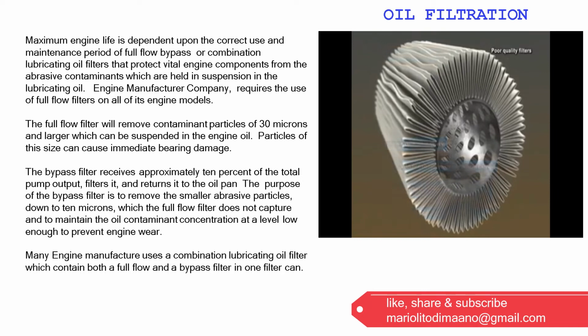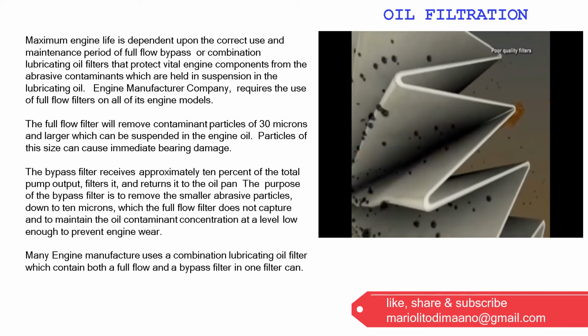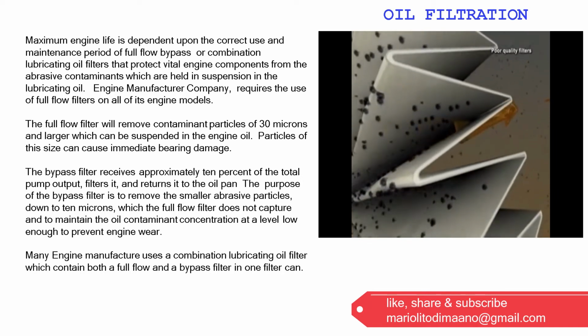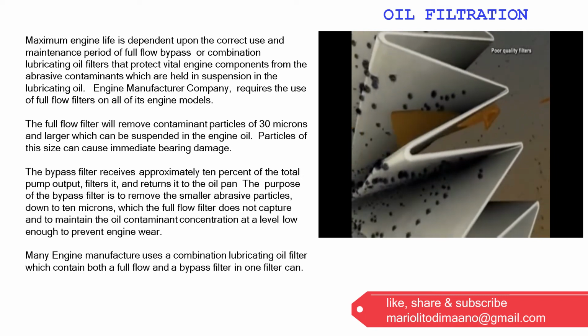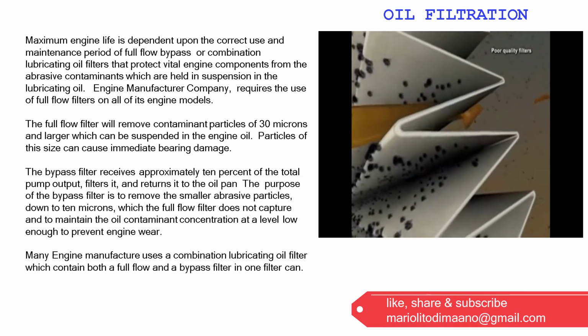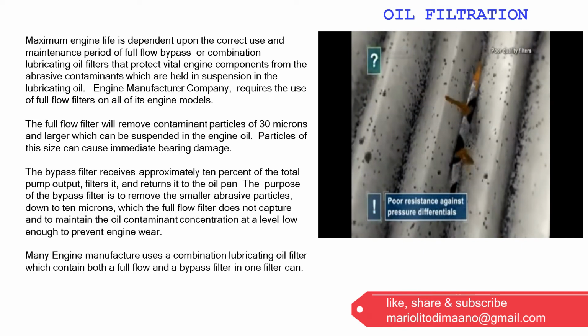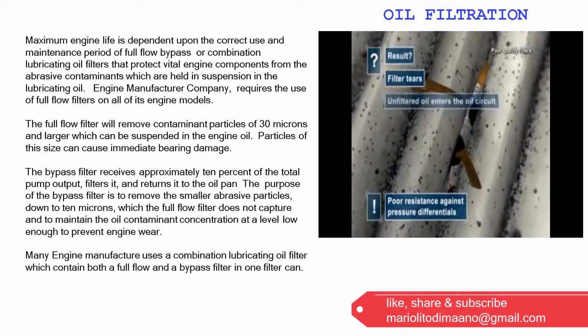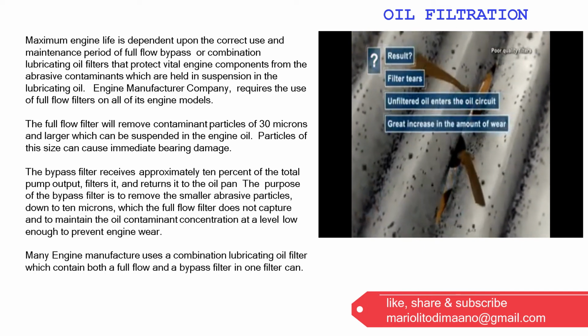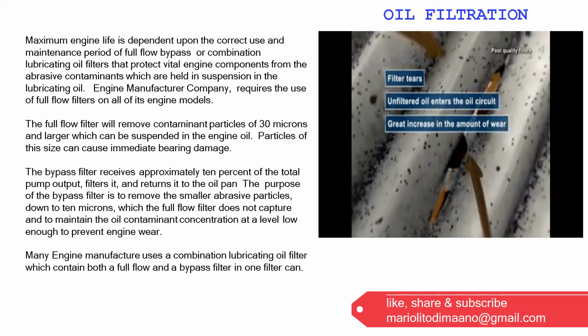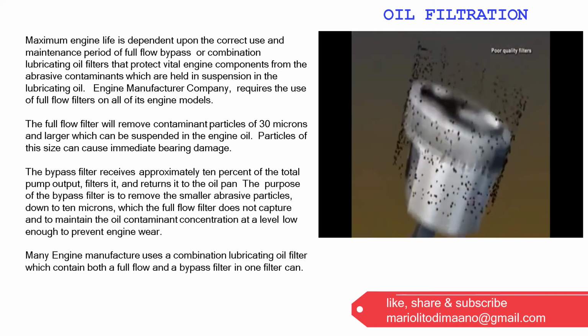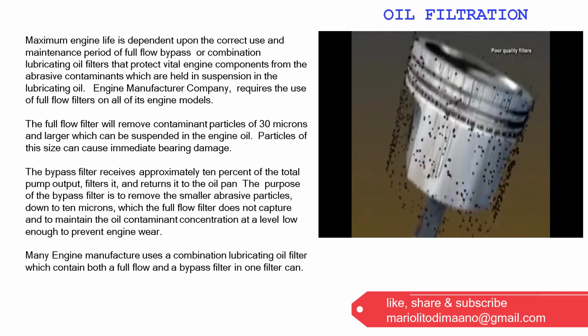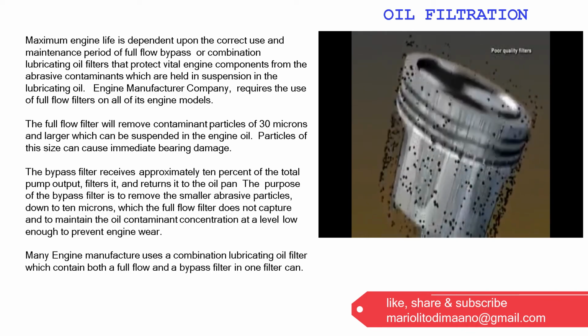Inferior quality filters do not have stable pleat geometry and have a lower dirt capacity. In addition, smaller particles are not retained. They remain in the oil circuit and cause increased engine wear. Poor quality filters can also tear easily when exposed to high-pressure differentials. Unfiltered oil therefore reaches the engine and within a short period of time causes substantial damage.